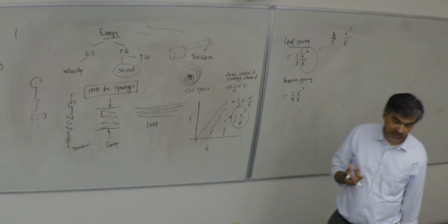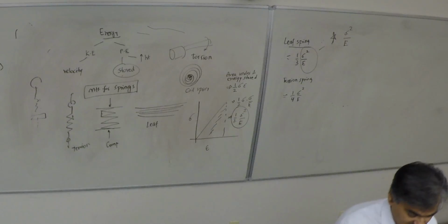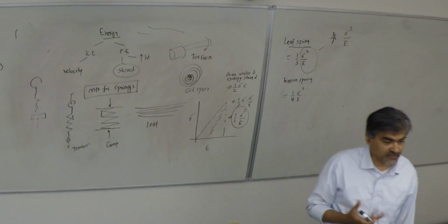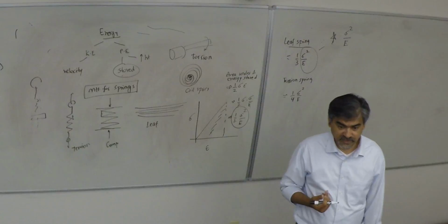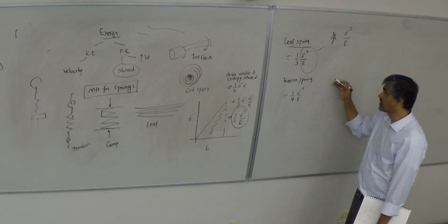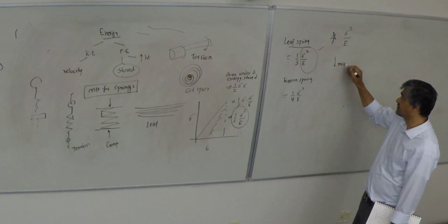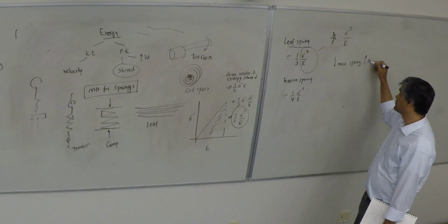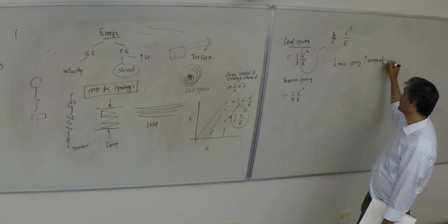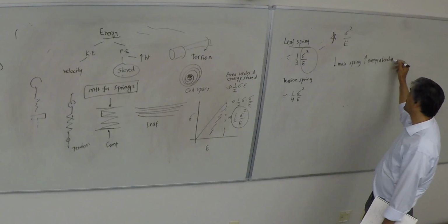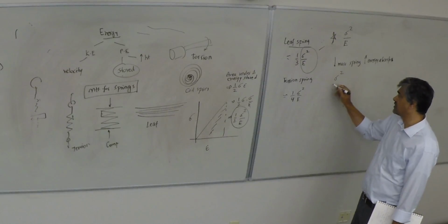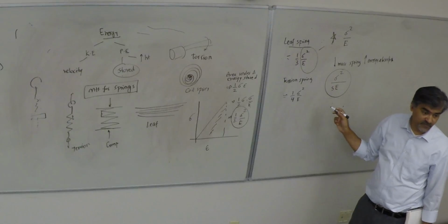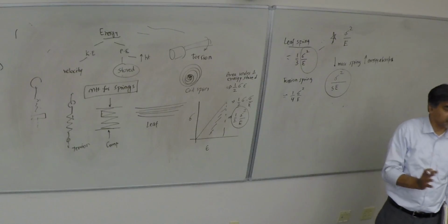So this is based on the volume of the part, etc. But we have not yet worried about looking at the weight of the spring. There is no mass term or density term on there. So when you want the minimum mass spring for the maximum energy absorption, you have to now consider that this factor sigma squared has to be looked at versus rho E. So the energy is a function of density.